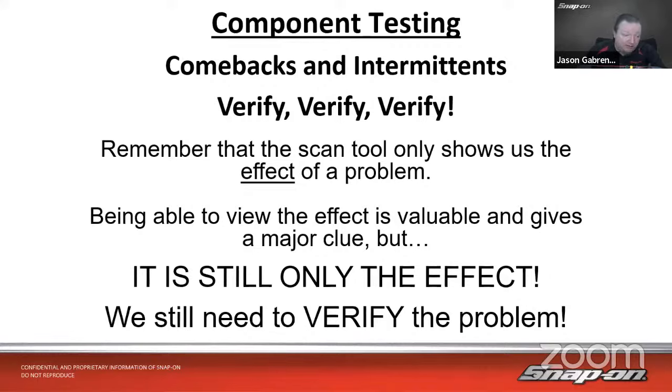A car comes in with a P0102 code, mass airflow sensor. So you go through, check the flow chart if you have one, and you say, all right, well, according to this, I guess it needs a mass airflow sensor. So I'll call the parts store.